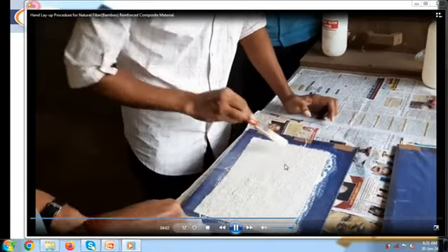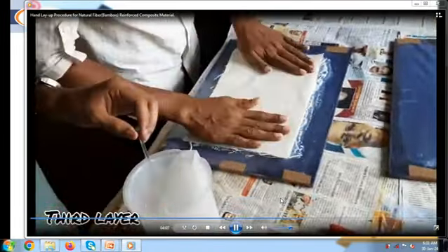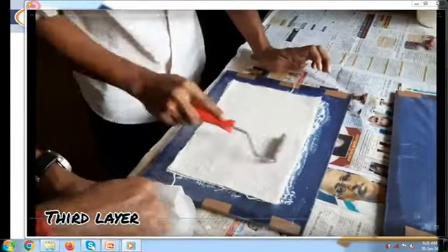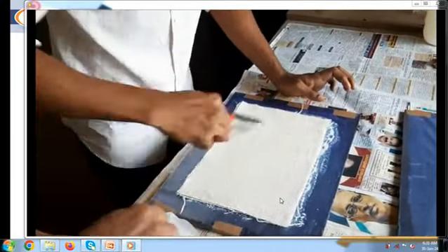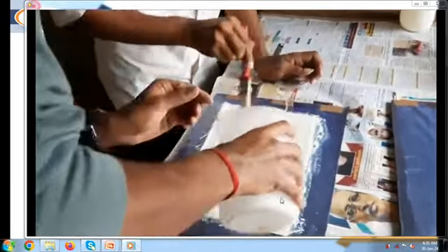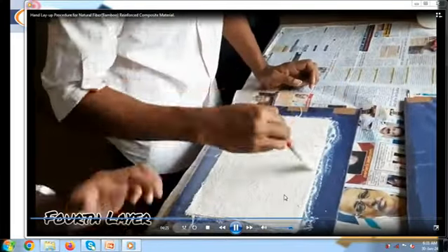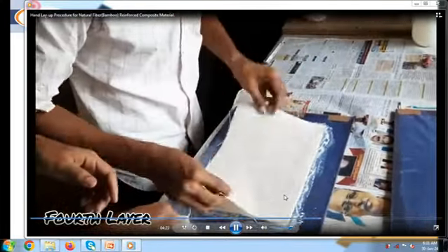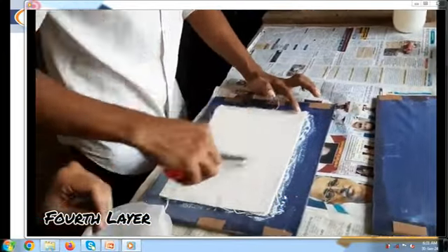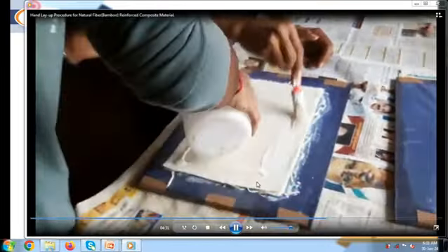So this is one lamina of bamboo fiber. We are now adding all those laminas together so that we can form our laminate. Here a roller or brushes are used to apply this resin thoroughly. You have to make sure that all the resin is dispersed properly on these fibers.